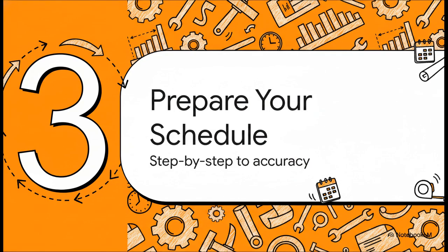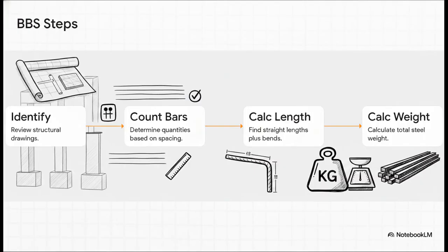Okay, part 3. Preparing your schedule step by step for maximum accuracy. We know it saves a ton of money, so let's actually walk through how to put one together. It helps to think of this almost like a recipe. Step 1, you identify your structural members, your slabs, beams, columns, straight from the engineering drawings.